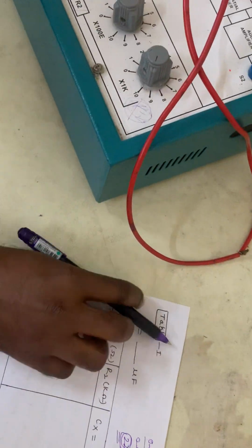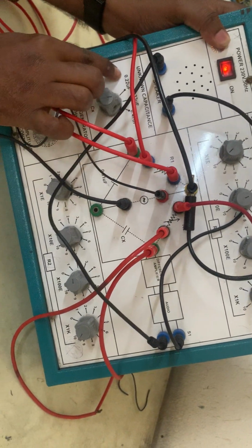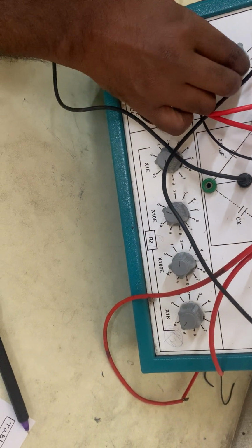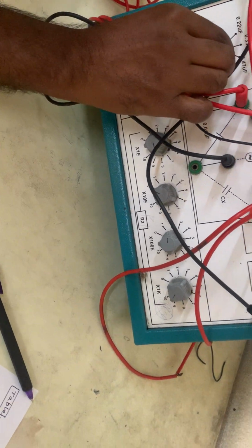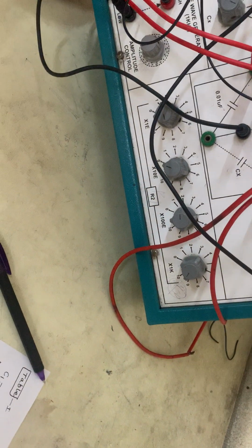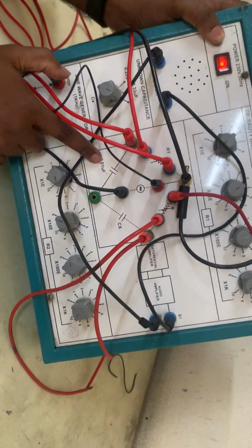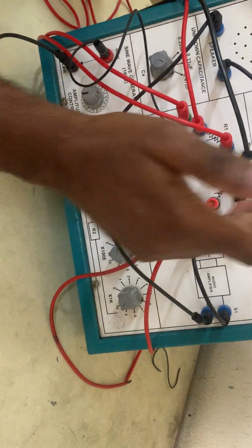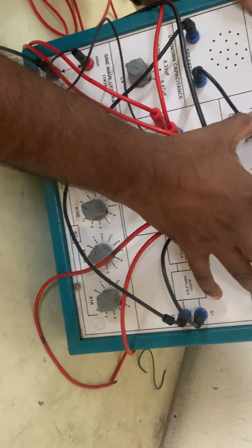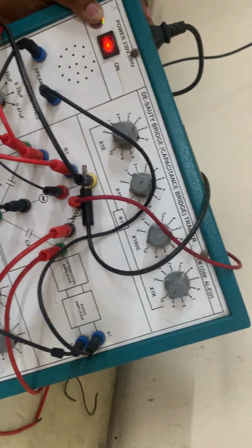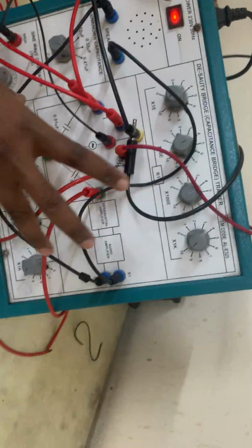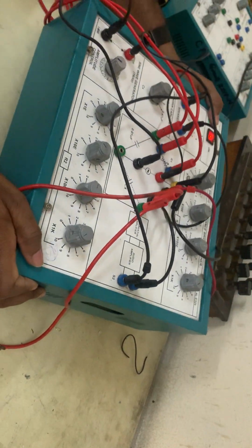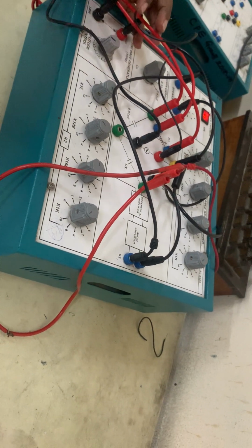Not only that, capacitance, how many values are there? This is 0.02, 0.003, 0.47 you have to take. First time 0.22, 0.33, 0.47 you have to keep. Based on that, one capacitance is fixed. You calculate the minimizing resistance. Clear? One is fixed, one more is variable. Resistance is variable. So like this you have to balance that. Whenever the sound is minimized, that resistance you have to calculate. That resistance is the balancing resistance you have to find out.